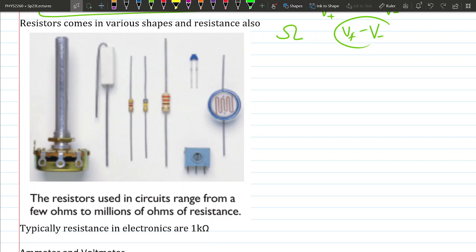Okay, you guys see that number? It's moving around because I'm not holding it completely still, like 0.4 ohm. So in reality, even a conductor has some resistance to it because it's not made of a superconductor. So that's one demonstration. A meter long wire will have a fraction of an ohm in resistance. That's just to give you guys some numbers.